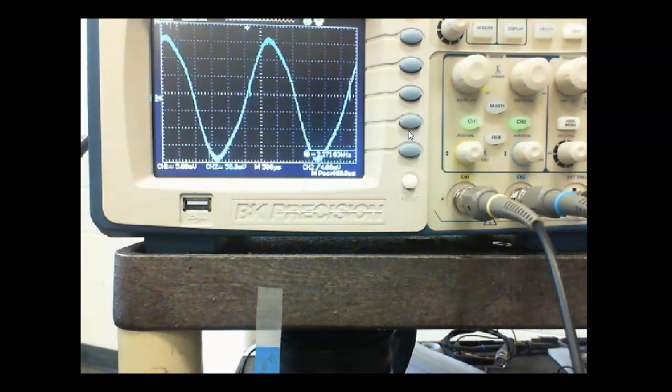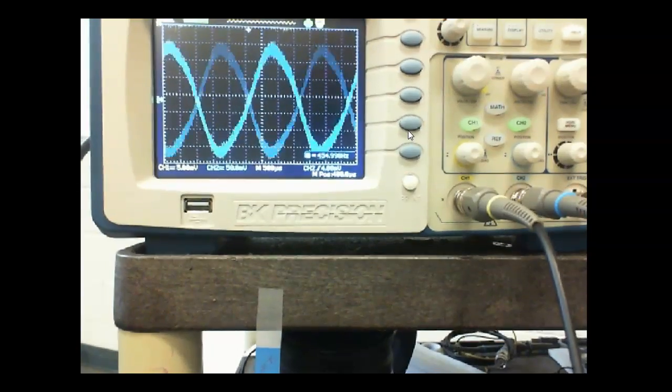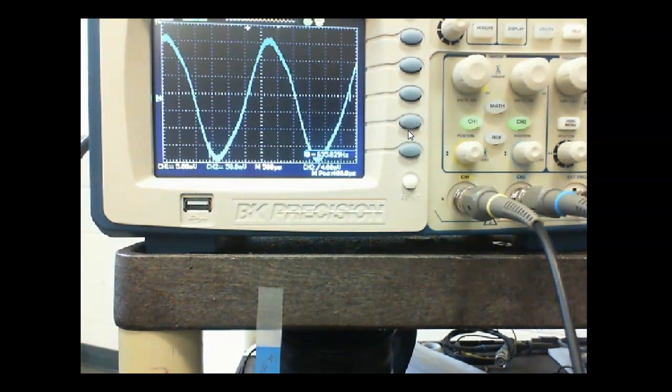So what we're doing is we've got V out set to its maximum. In fact, we could bring V in up a little more if it's easier to measure. And this is maximum. So right now I have my 10K pot set to 0 ohms, and I'm measuring the output. I'm going to start adding resistance to my 10K pot until this drops down to 1/2. As soon as it drops down to 1/2, I know the resistance I have set on my rheostat is the same as the input impedance of the amplifier. Then we'll measure the resistance of the pot to see what it measures.